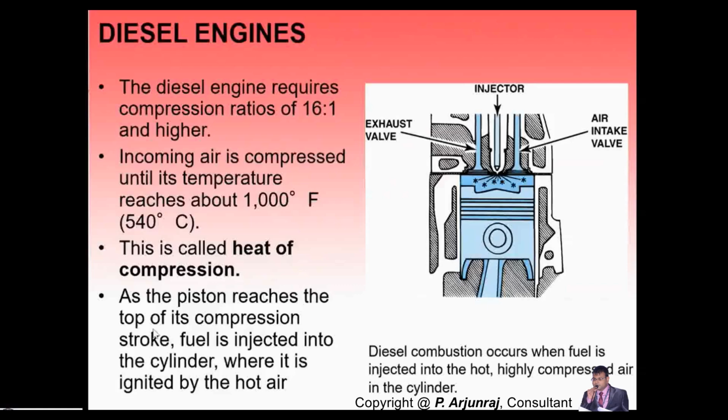As the piston reaches the top of its compression stroke, the second stroke, where the piston moves from BDC to TDC, and before it reaches the top, which means before the piston reaches top dead center, the fuel is injected into the cylinder, where it is ignited by the hot air.